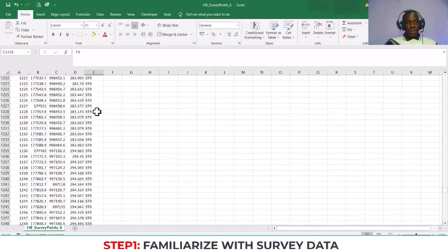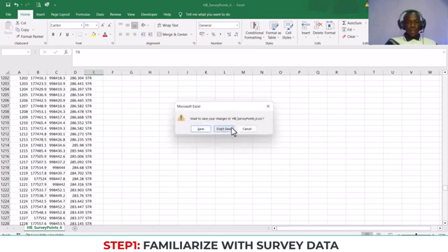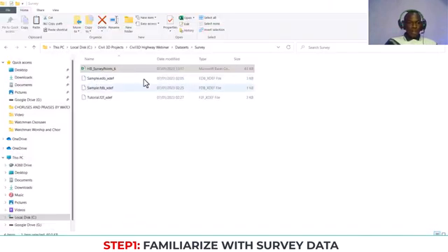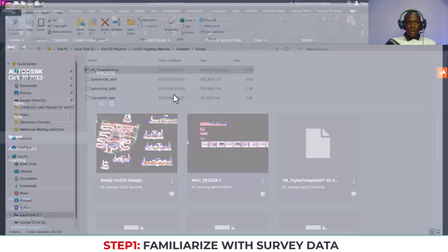There are 2 ways you can import your drawings to your points to Civil3D. It's either going to be in text format or a CSV format. In this case I've saved it as CSV points, so I'll not save that. This way I've saved it. This is the name. So now let's go to Civil3D already.